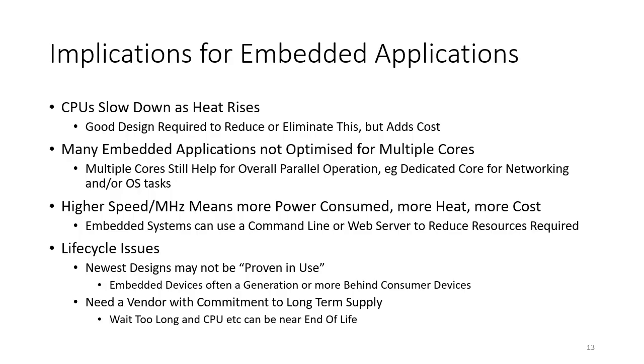And this is one of the reasons you'll see industrial PCs are quite expensive, because the vendors and designers of those PCs are managing that CPU design so that the CPU ideally keeps running as fast as it can all the way up to the maximum temperature. To do that, it's possible, but you need big heat sinks. You need special control over the voltages and the speeds in the first place. You might even end up underclocking a CPU, so that in order to avoid hitting those maximum temperatures, you avoid hitting the maximum speeds. So a lot of implications there, but that's certainly something you're very concerned about.